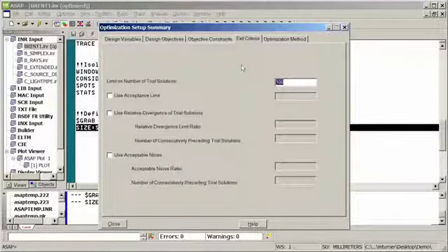The exit criteria page will allow me to define when I want ASAP to stop the optimization. Because global solution space is infinitely large, in theory the optimization could proceed forever. That, of course, is not reasonable. So as a minimum, you need to set a limit on the number of trials. You can also set a value based on how close to your merit function you need it to be, what the divergence limit is.